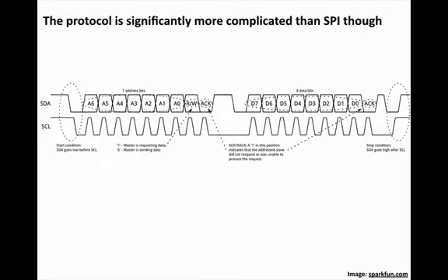Then you send it a command, and you can either read data back from it during that, or you can send it a command. So with these packets, there's a lot more overhead. We're having to say, okay, this device address, read write, then do your transaction. The next time you want to talk to that device, this address, read write, do your transaction. So it's not as fast, but it has a greatly reduced number of wires, right? There's no selection line, and you only have the clock and the data lines to worry about. But it is at the expense of complication and speed.